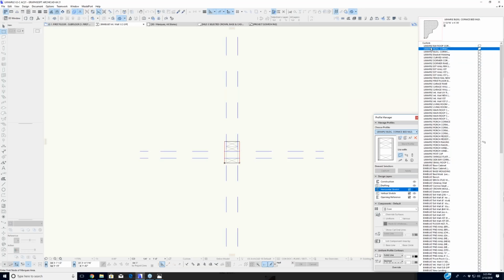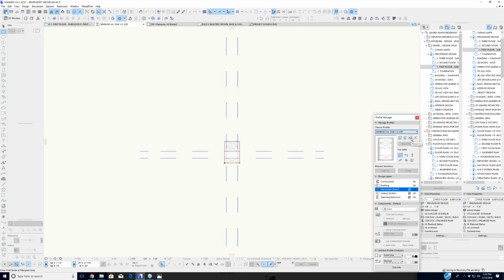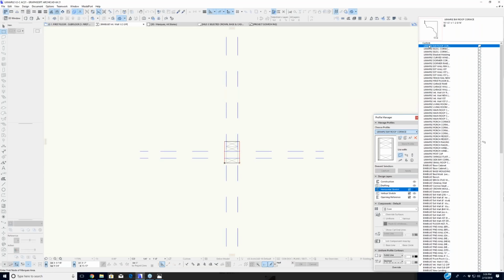If I come up with a complex profile, a surface, a model part that I made, anything, I'm going to know right away that it is pertaining just to this file. And the way that I get all of these to show up neatly up top is when you name your file, that's this button. If I click on rename, you can see that you can add a space. So if there's one space right now in front of there, just a blank space, that puts it up top. If I put 2 in there, it's going to jump alphabetically all the way to the top. So right now you can see if I scroll through, these are all components that make up either a rake or a complex profile or a water table or a hand railing pertaining just to this project. And you can see I come through here. Now, if I pick this one up, let's see, I'll come through just to show you a few more of these.